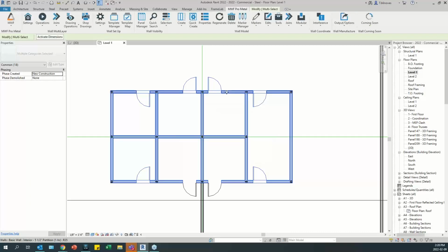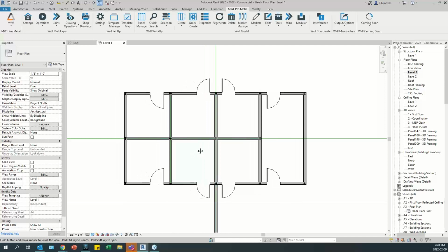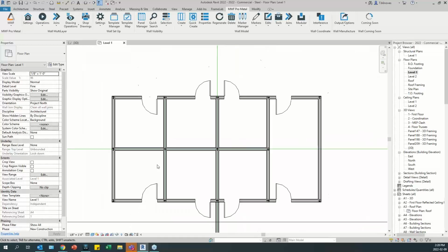And if we didn't create any rules for a specific condition, it will throw you an error. It didn't here, but let's say I forget to create a specific rule for the cross-section intersection here. We would see an error warning telling us that it couldn't find any rules for that location. And that's fine. If you see that warning, don't worry about that. Usually it's just going to place all the other ones, and you can check what corner does not have the join marker. That would be the corner that you need to create a rule for, okay?